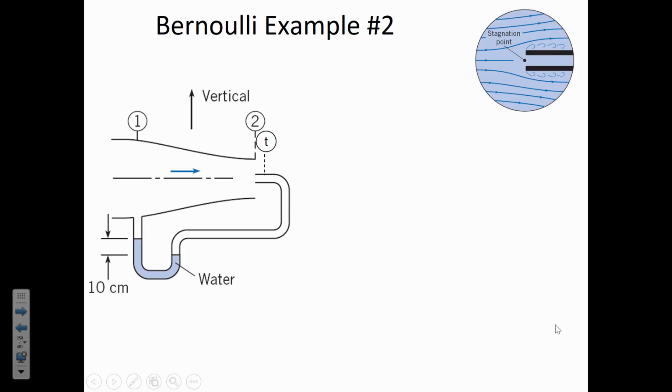Because all of the velocity that the wind had, once it bumps inside of the tube, that kinetic energy is going to be transferred into additional potential energy in the form of extra pressure. So there's going to be more pressure inside of the tube than there is just outside of it at location 2. In any case, I just wanted to clarify that everywhere inside of that differential manometer where we have a gas, the pressure is the same.